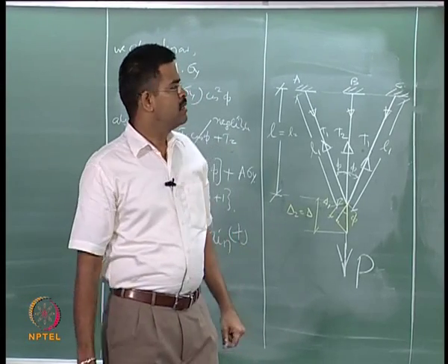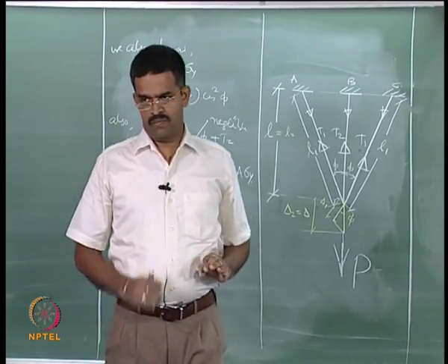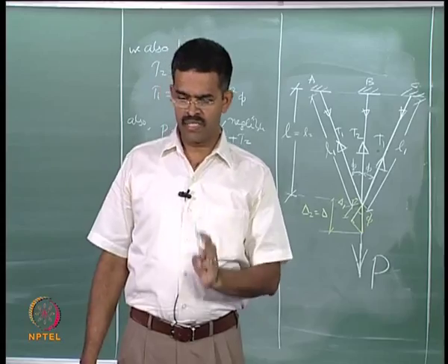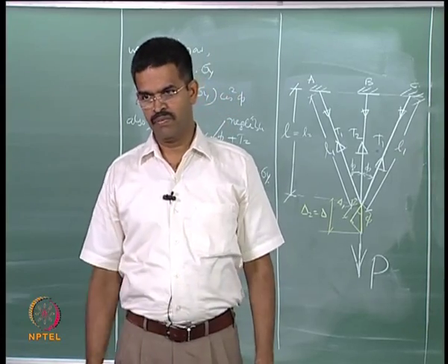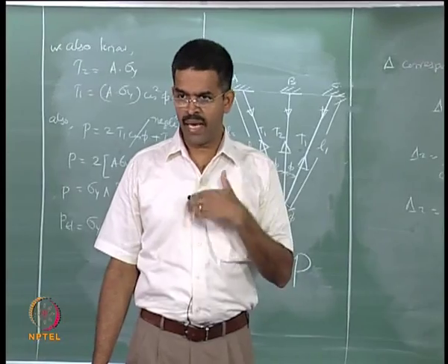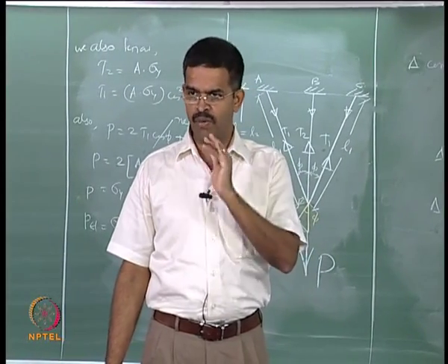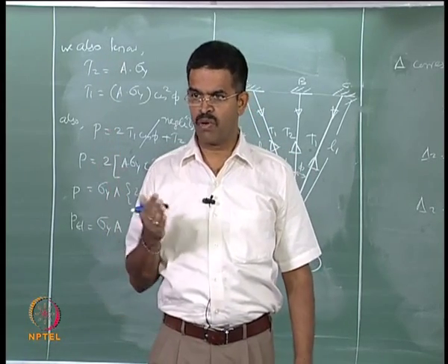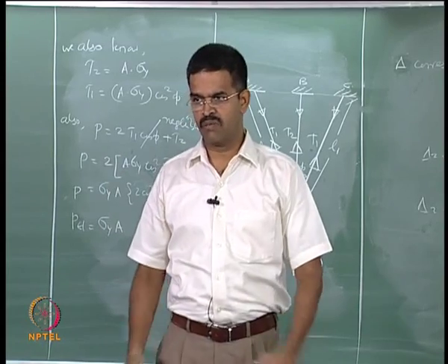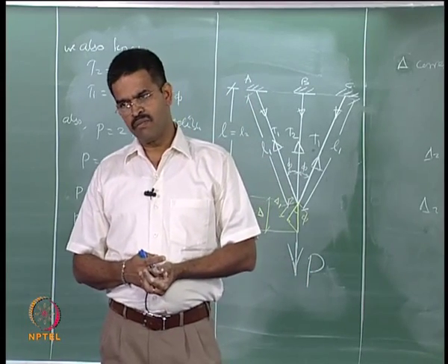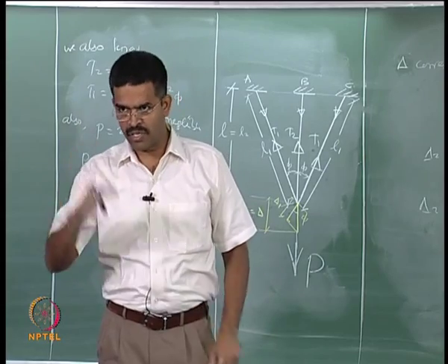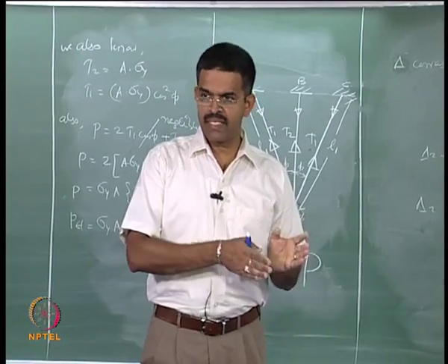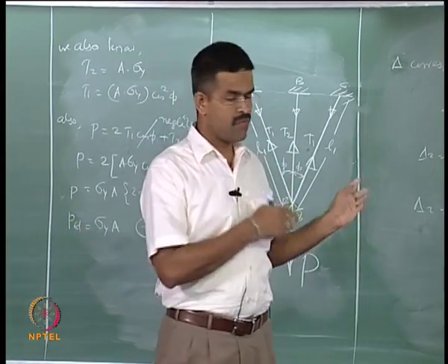Is that clear? So it is very clear from this lecture that a transition from elastic to plastic is mandatory, because I want to use the excessive reserve strength available from the first yield point. Marine structures are made out of steel, and steel has the first yield point not because of the load phenomena, but because of residual stresses set in the material by some other manufacturing and construction process which are initiated in the marine structural system design. So they can be eliminated, completely is not possible, but partially can be reduced. The presence will significantly cause what we call an inelastic behavior in the system, apart from making the failure brittle.